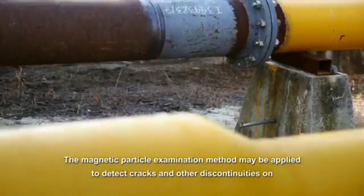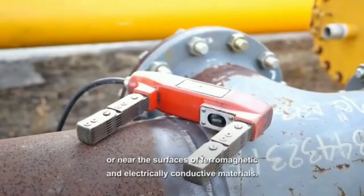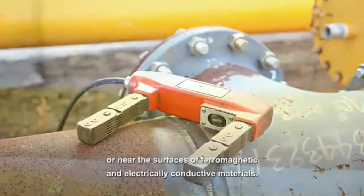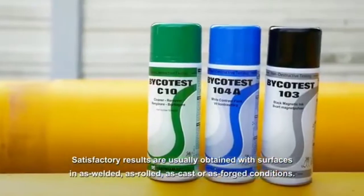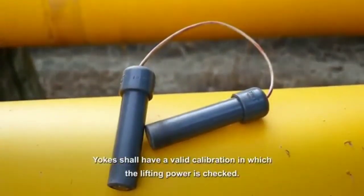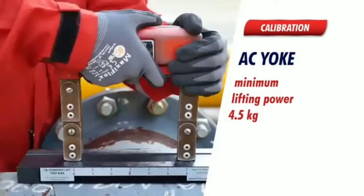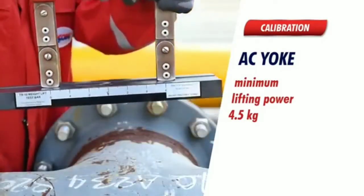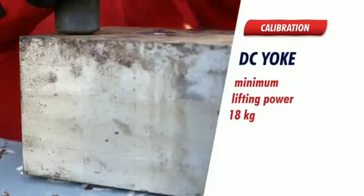The magnetic particle examination method may be applied to detect cracks and other discontinuities on or near the surfaces of a given material. Satisfactory results are usually obtained with surfaces as welded, rolled, casted, or forged conditions. Yoke should have a valid calibration in which the lifting power is checked. A yoke is an equipment used to help carry or pull heavy objects by distributing the weight evenly on both shoulders or sides. In this video, AC and DC yokes are used.